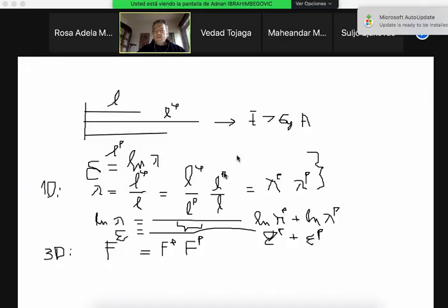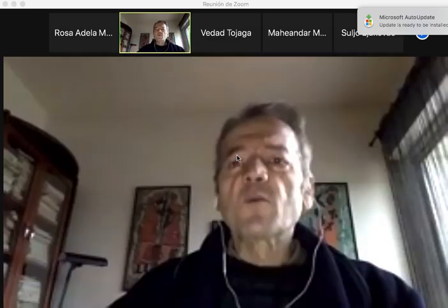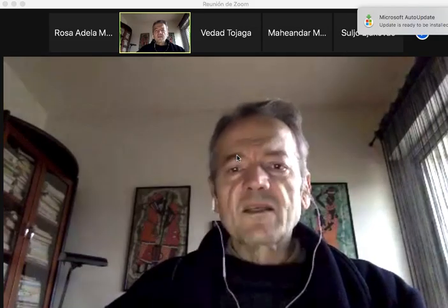The stretch is split into multiplicative elastic and plastic stretch. And if you take a logarithmic strain measure, that becomes the plastic strain plus elastic strain, additively decomposed. So it becomes a standard way you compute plasticity plus the standard way you take into account large deformation. It becomes just a superposition of two nonlinearities. This is really the biggest merit of this approach because it splits the geometrically nonlinear and material nonlinear problem. And you really can build your formulation in a very nice and, let's say, modular way in this manner.